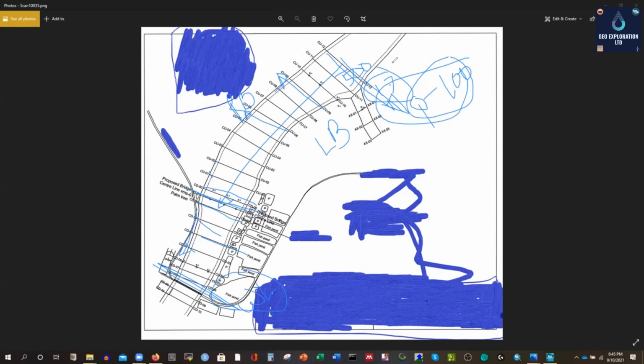So today I'm going to show you how to create the geometry in HEC-RAS. If you have any survey data as an Excel file, we have to be able to create the geometry. I have this data ready, so I'll insert this data, and the model I'll run today will be steady state, so there won't be any time series. One value of Q will be fixed for the entire time, and one value of water level will be fixed. Okay, so that's that.